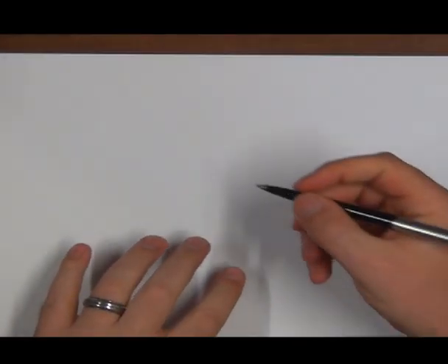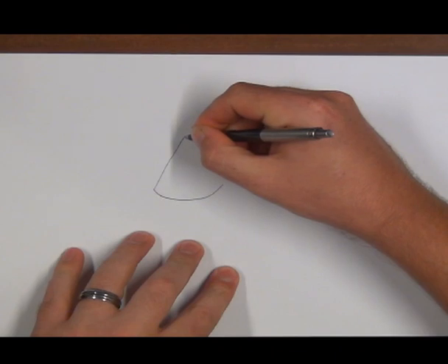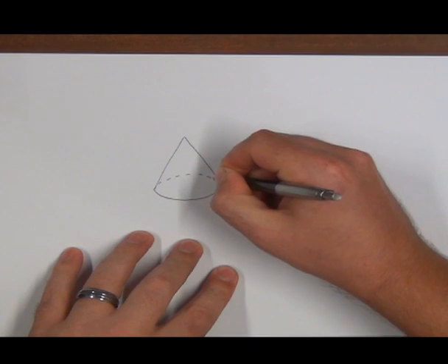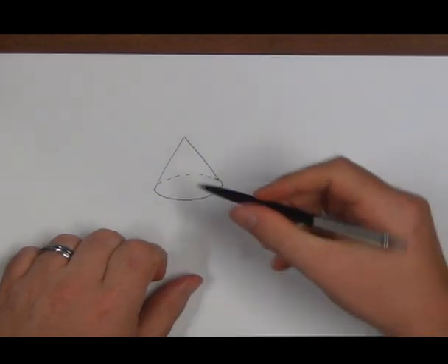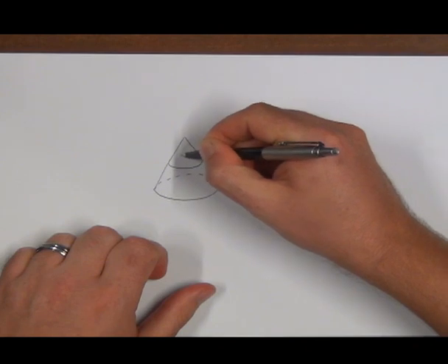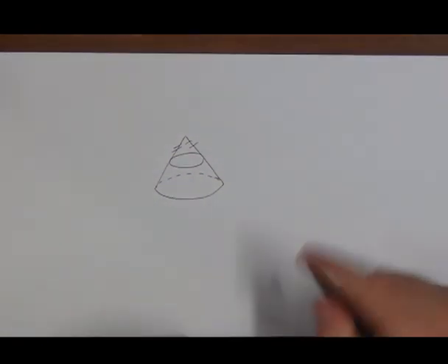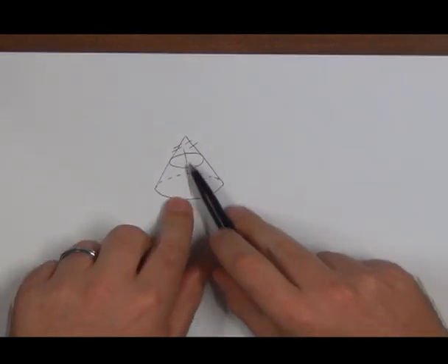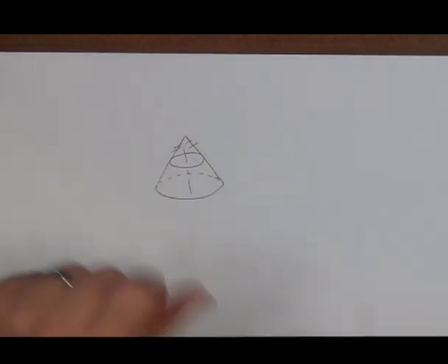So, if we now imagine something like a cone, okay, there we have a cone. Now let's go and cut the top off of this cone. Something like that. Okay, so this cone is a cylindrical component because it's symmetric about an axis. So to fully define a cylindrical component, we need two views.